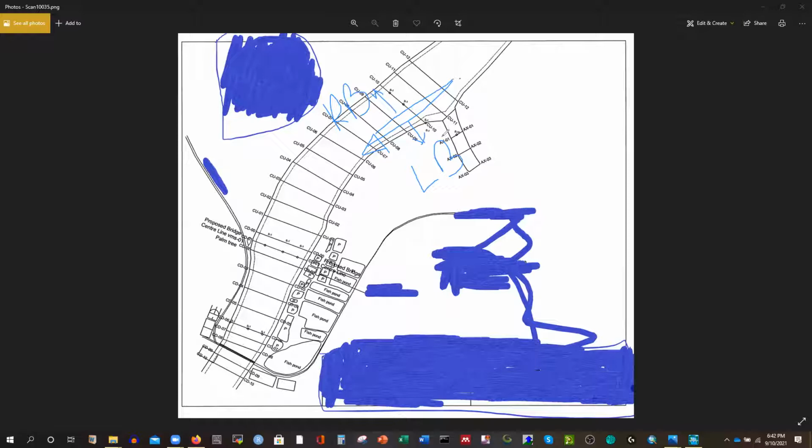In this plan, we have to survey in such a way that we can measure the cross section from left bank to right bank, because the HEC-RAS model can take the cross-sectional values from left bank to right bank. So that's what we did here.